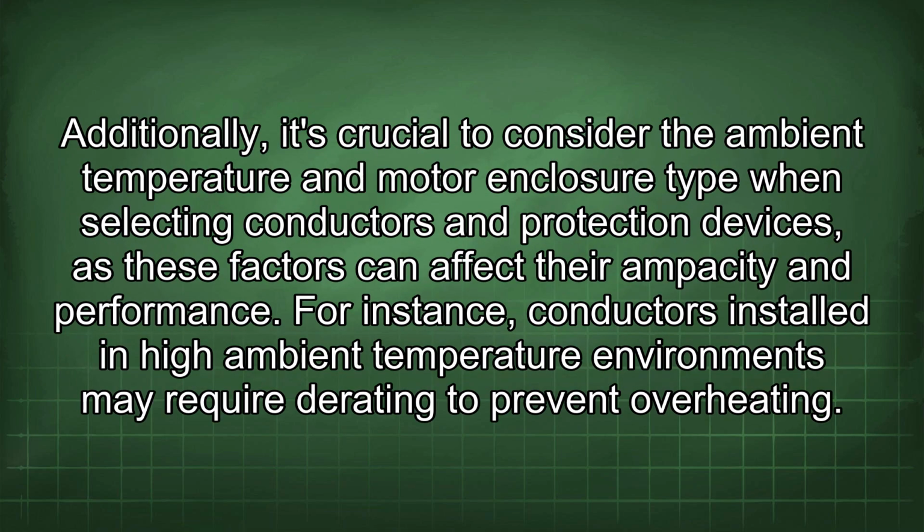Additionally, it's crucial to consider the ambient temperature and motor enclosure type when selecting conductors and protection devices, as these factors can affect their ampacity and performance. For instance, conductors installed in high ambient temperature environments may require derating to prevent overheating.